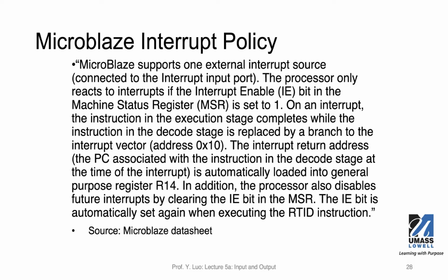And this pin is connected to the interrupt input port. The processor only reacts to interrupts if the interrupt enable bit in the machine status register is set to 1. So this interrupt enable bit in this MSR is set to 1.